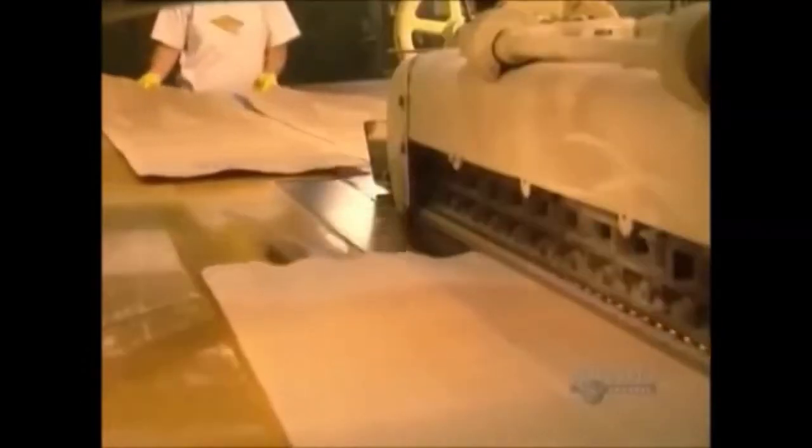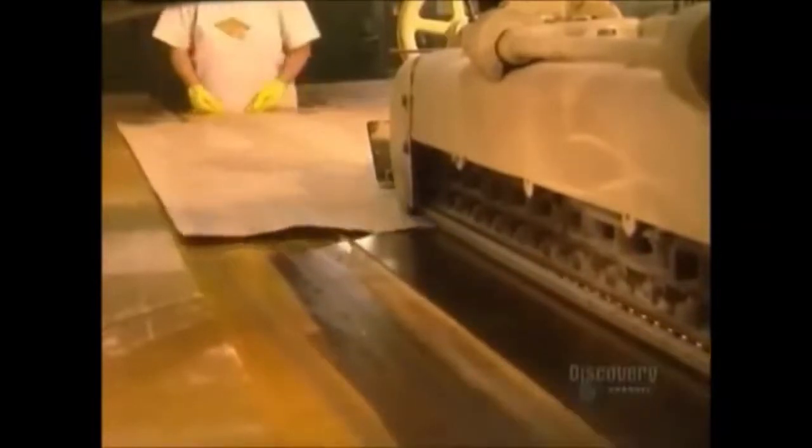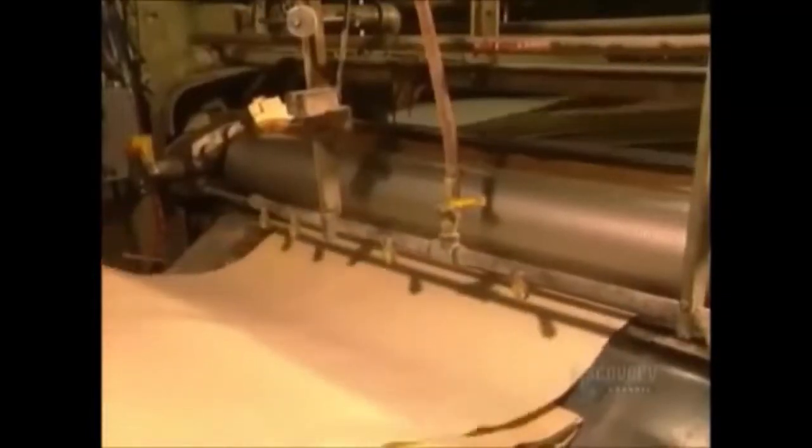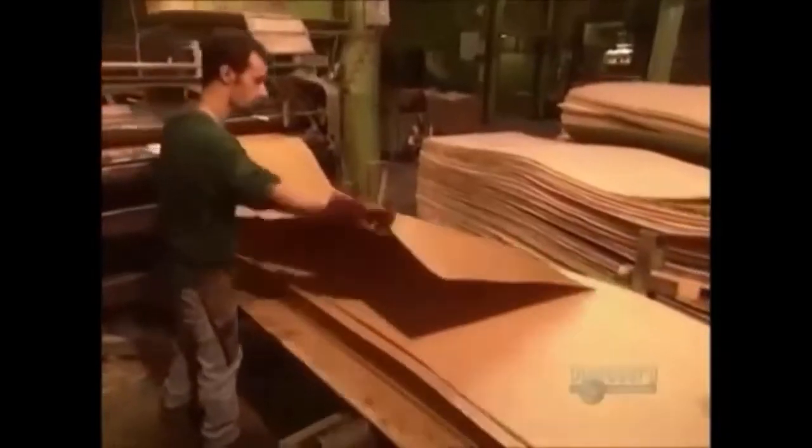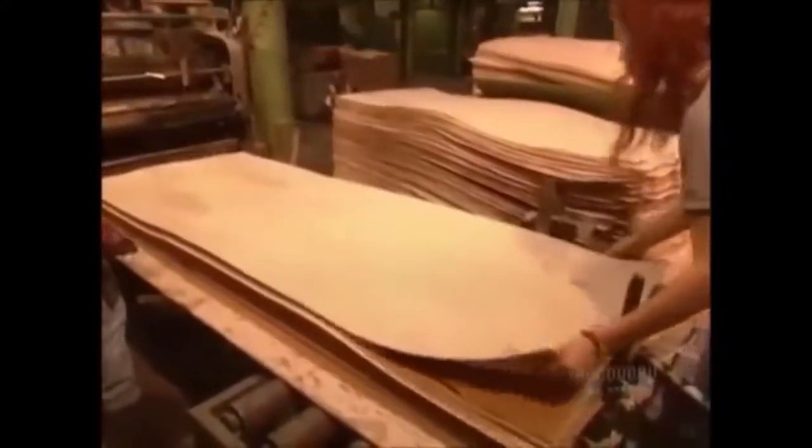To make veneer sheets for the front of the plywood door facing, the side that will show, they line up the wood's grain and other features in mirror image. For the back, the side that won't show, they assemble the defective parts they cut out earlier. They use 3 veneer sheets to make up the plywood door facing. They apply glue to both sides of one sheet, then sandwich it between 2 other sheets.